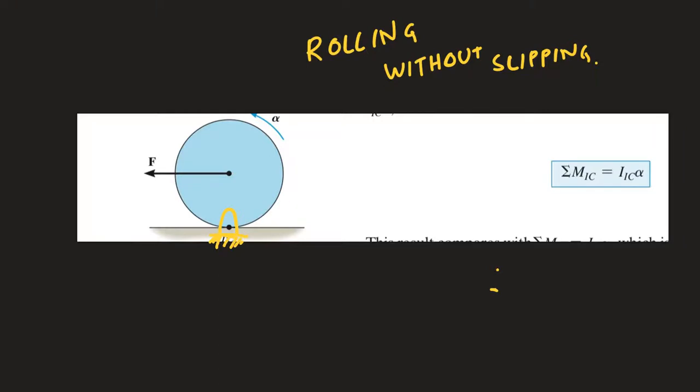For another instant, there will be another instantaneous center. So you can apply all these equations throughout the motion, but the instantaneous center will be different, but all equations will be applicable. So given that, you can think of this thing undergoing a pure rotation about this pivot point, then the equation of motion will boil down to this. You simply take the sum of moments about this particular point, which is the instantaneous center, and equate it to the product of